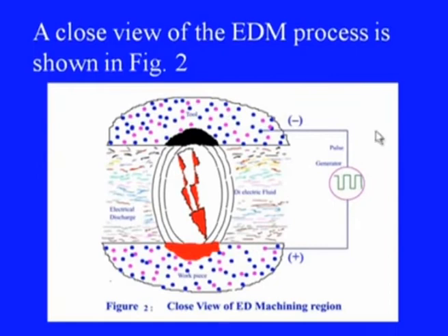So, this figure depicts actually what happens in the sparking zone as we apply the electric field across the tool and the workpiece. So, this is where the dielectric is, this is the voltage applied across them, and as the voltage increases to a particular what is called discharge voltage, this dielectric column or the dielectric present in this, the nearest point gets breakdown and plasma is created here.